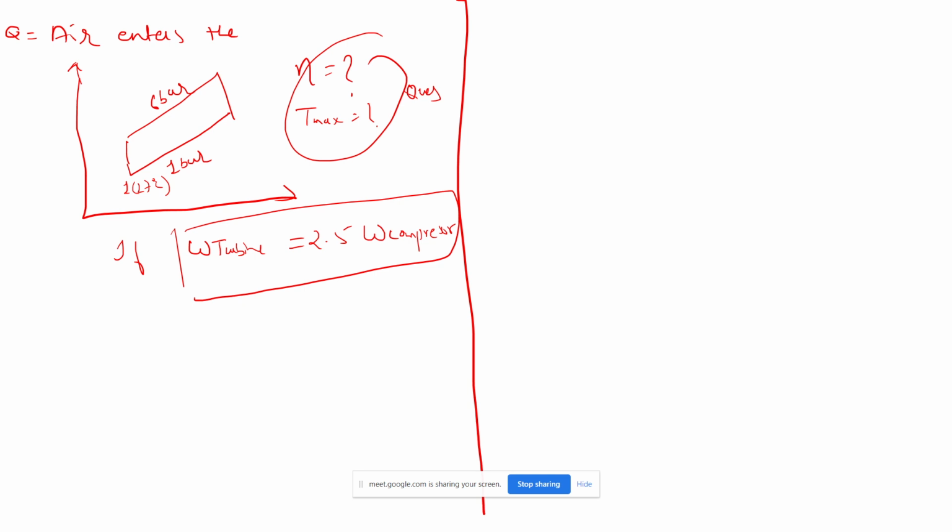Sir, can we take gamma is equal to 1.4? Yeah, just take, wait, I'll write that also because many of you might have been confused. Gamma take 1.4 and CP if you have asked, just take 1.005 kilojoule per kg Kelvin.